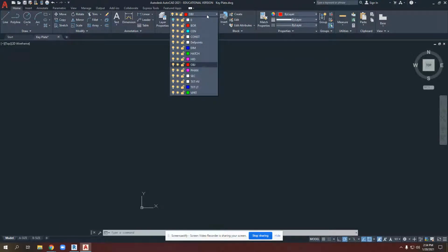If you were to download this software at home, unless you use a template file, you're going to be using a default file which has much less in it. For instance, all these different layers will kind of replicate different line types that we might need for our drawings.